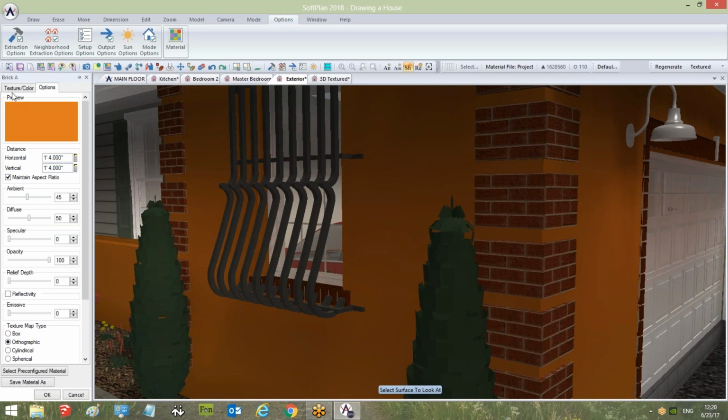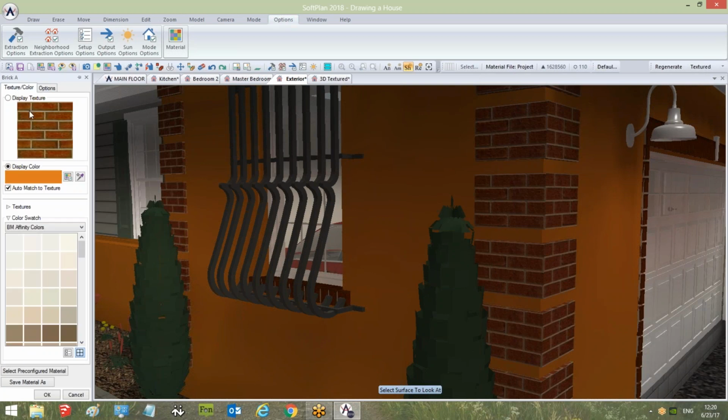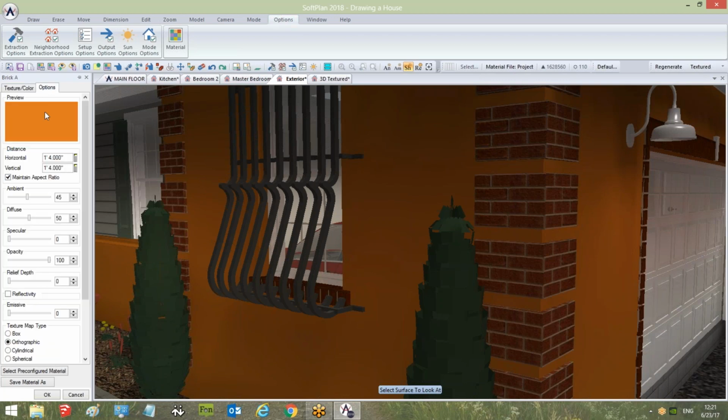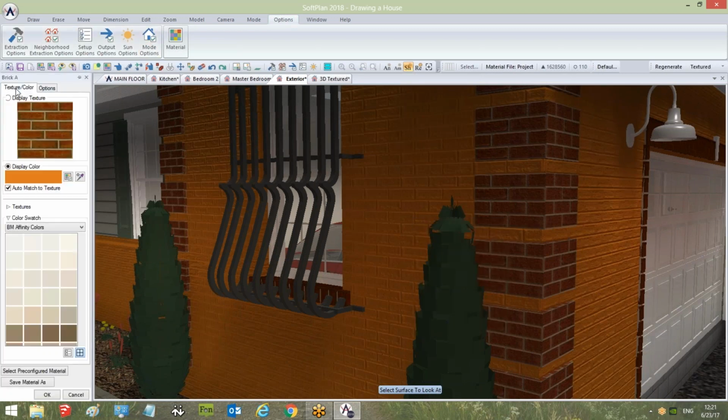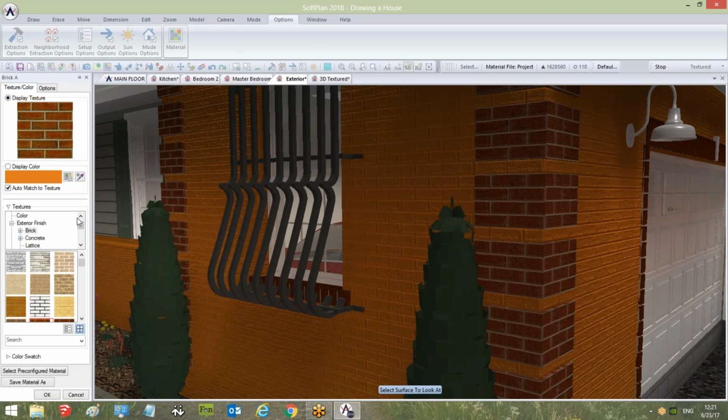So just so that you know that you could apply a custom color to a texture, that's how you could do it. So enable display color, choose the color that you want to use, and then finally increase the relief depth. Typically between 60 and 100 might be the value you might like, so that it's not too obtrusive, but it's nice to see. There we go. And now I'm just going to bring that back to use our default texture here.